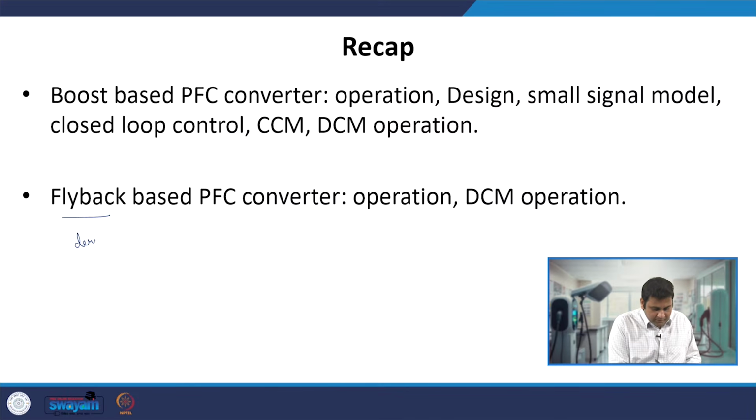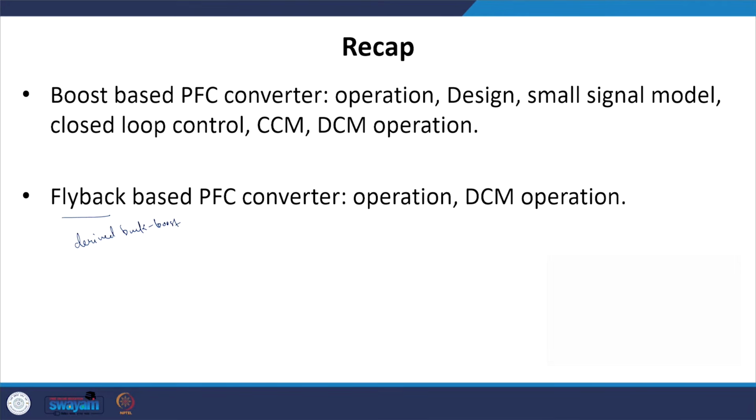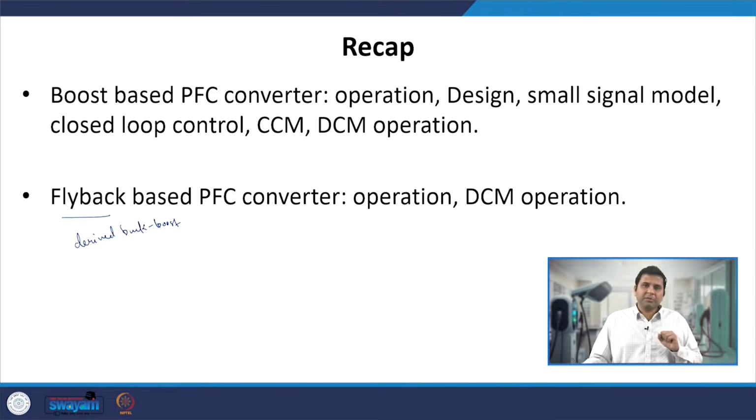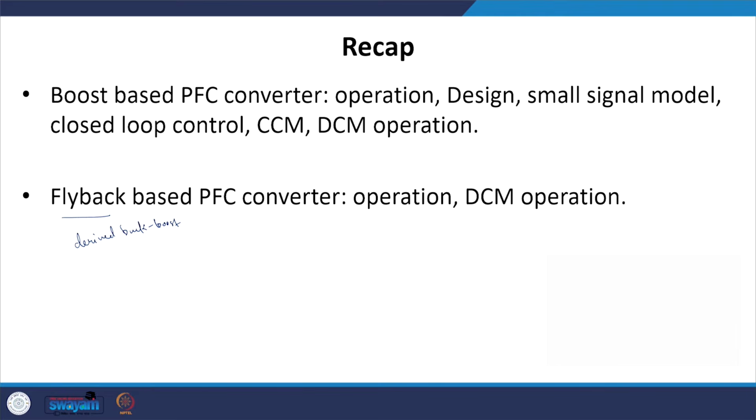And then we have also seen how the PFC converter can be obtained using a flyback based converter, which is a derived buck boost converter, or you can say it has the same concept as the buck boost based converter. So we have also seen buck boost based PFC converters and their operation, particularly the DCM operation, because during the DCM operation it acts as a voltage follower mode, or the effective input impedance of this converter is purely resistive, and thus the unity power factor current is drawn from the AC voltage source.